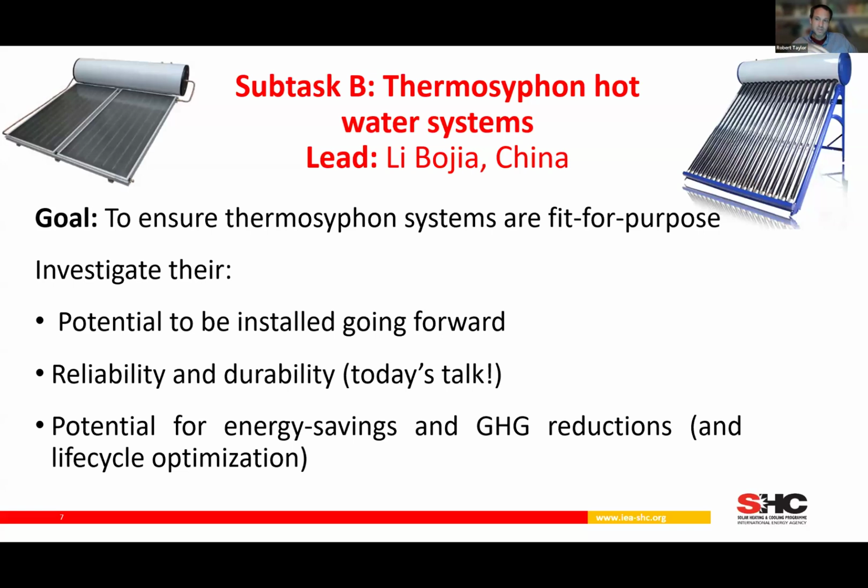In both cases, as the water heats up, it expands, and that difference in density causes the hot water to rise up into the tank, and then the cold water from the bottom of the tank falls down into the collector, and you get a nice natural circulation there, and that's why you don't need a pump. And then, of course, from that tank of hot water, you can extract water and bring it down into your house for washing dishes or cooking or taking a warm shower.